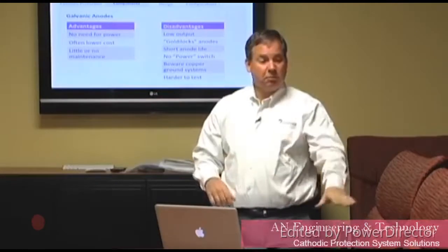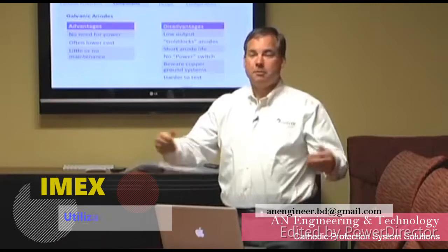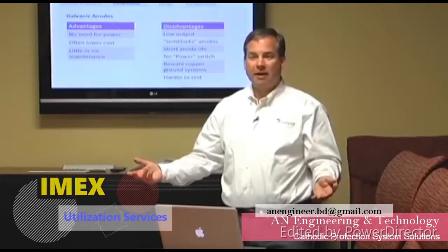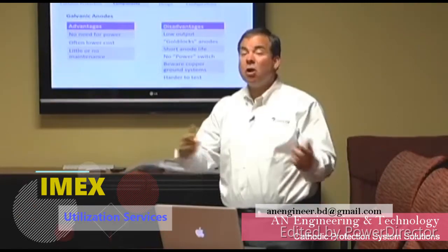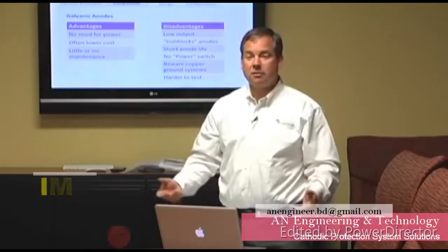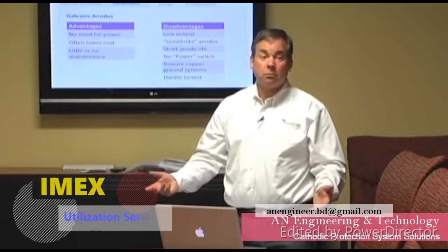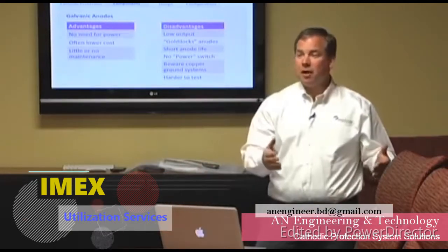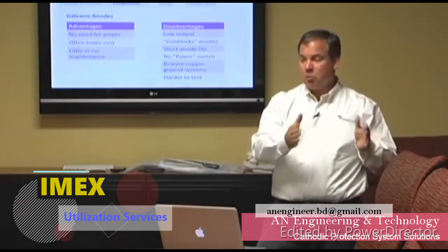The galvanic anode system is buried, the pipeline is buried, it's forgotten about. 5 years later and nobody's testing. In fact, I got a call yesterday from a guy. He's got a pipeline protected with galvanic anodes. I asked him, have you had it tested? He says, no. Do you know it's working? No. Now, if he had a rectifier and a power supply, he could look at the power supply and say, yep, it's still working, it's still working.